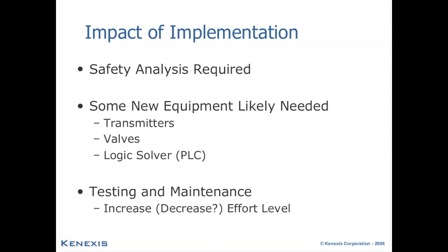We are frequently asked, well, okay, what if I decide to implement this in my plant or process, what's going to be the impact? There will be a significant amount of analysis that is required, and certainly some, although not all, new equipment will likely be needed to cover situations where the existing systems are not adequate to achieve the SILs that are required of them, or situations where new safety functions need to be added.